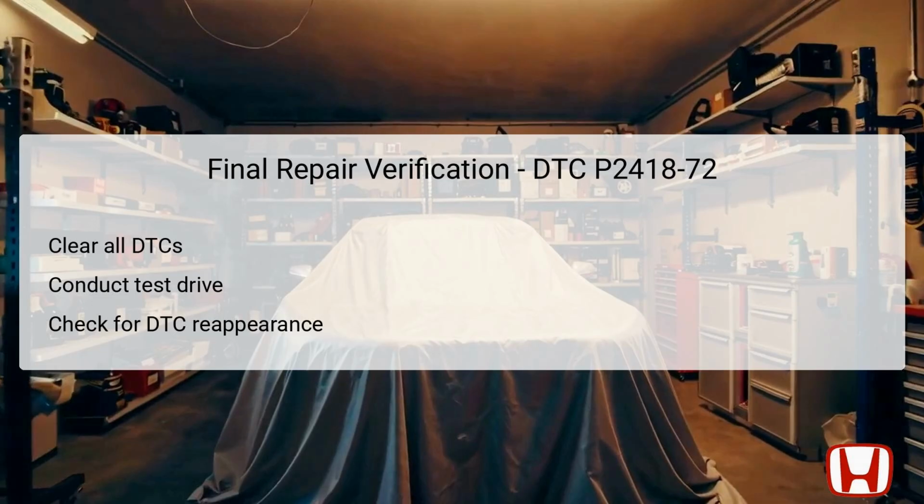This ensures that any previous faults no longer influence the vehicle's performance metrics. Following this, a test drive is recommended to validate that all systems are functioning smoothly and as intended. It is important to monitor the vehicle closely during this period for any signs of irregular behavior or abnormal noise, particularly from the EVAP system. After the test drive, a further check for the reappearance of the DTC should be conducted using the HDS. If no codes resurface, it confirms that the repair has been effective and the vehicle is running correctly.